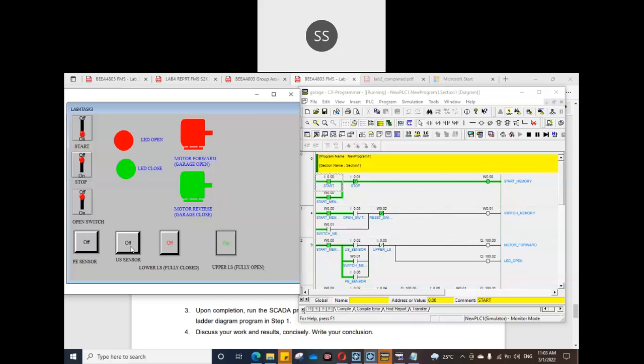So it's closing, and the upper limit switch is no longer in contact, so the upper limit is off, because the garage door is closing. It goes down until the lower limit switch hits, so the motor is stopped. So that's how it works. It waits until the next car comes.